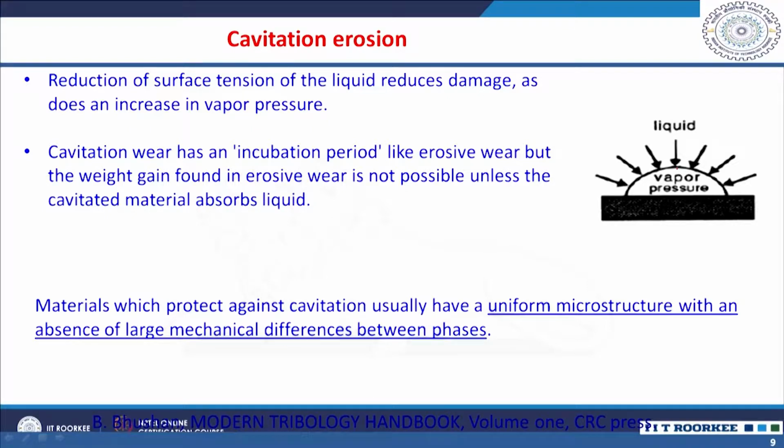So, weight measurement is not a prominent technique to assess cavitation erosion. The materials which protect against cavitation usually have a uniform microstructure without any difference in the mechanical properties between the phases. So, you will have minimum cavitation erosion, right.